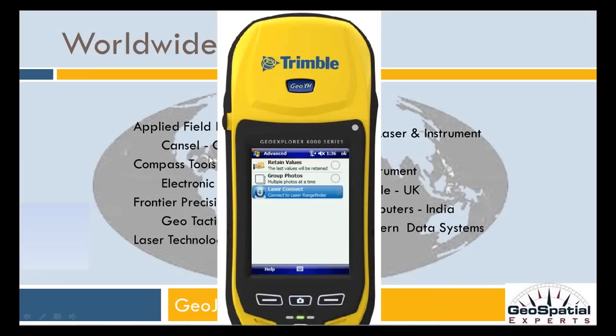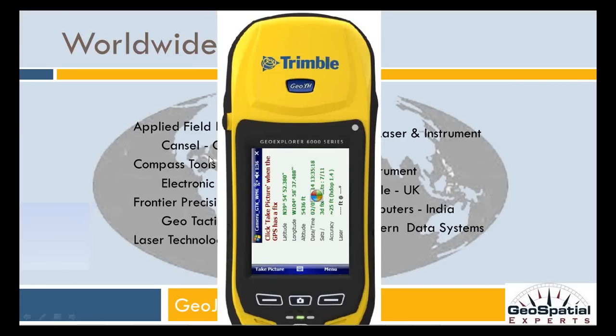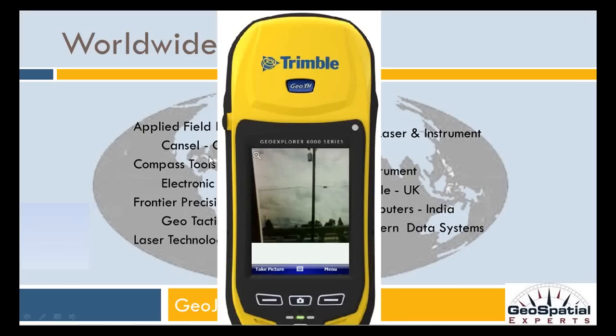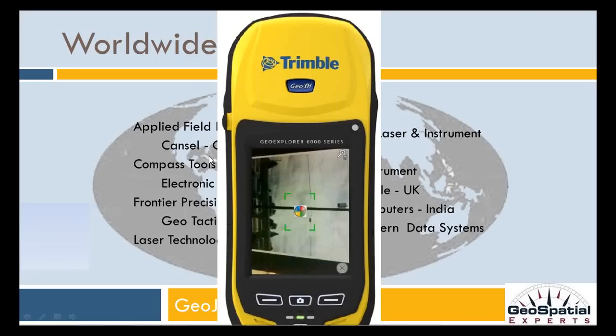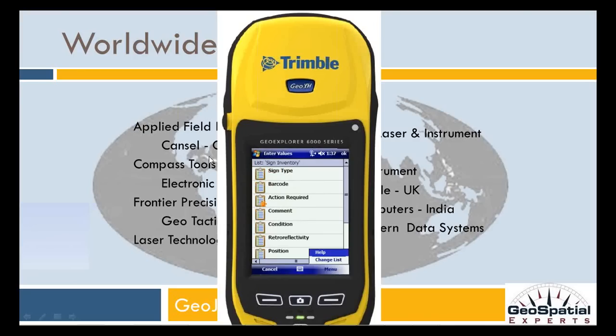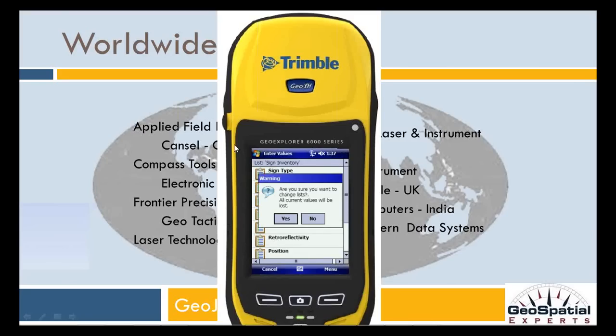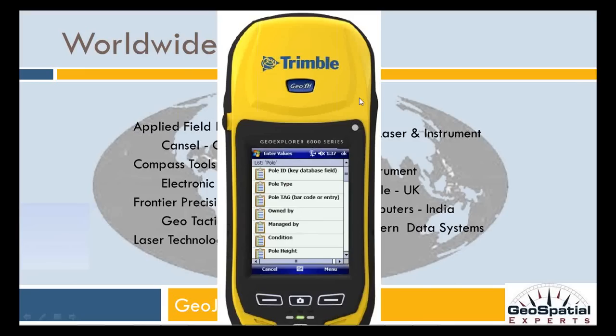And now that I'm connected to the unit, I can say, well, I want to shoot some distances. GeoJot supports that. Let me come in here to the camera, and what I'm going to do is take a picture. Now, when I take this picture of the pole, it's going to save, bring me to that attribute list area. Now, from that attribute list, I still have signs up. So what you're going to want to do is menu, change list, and I do have a pole inventory list in here. So I can set that for OK. Yes. It'll switch me over to the pole list.